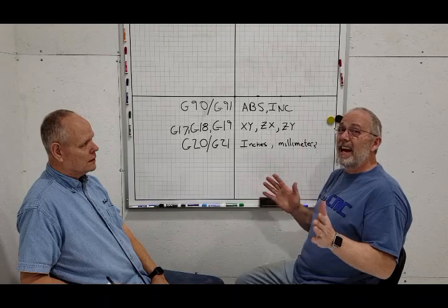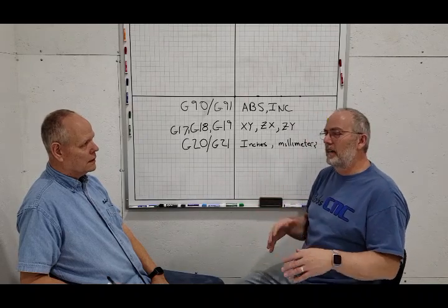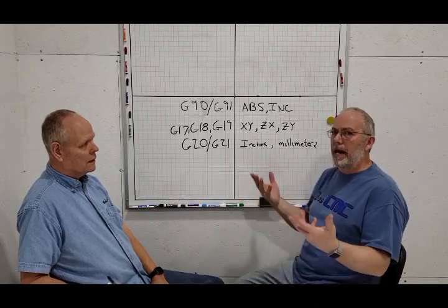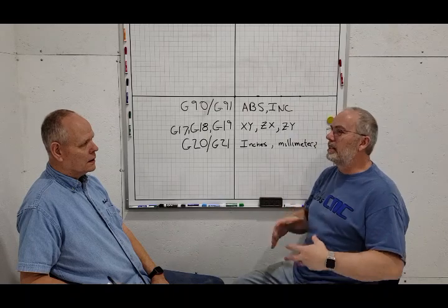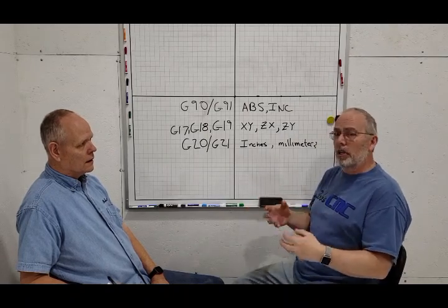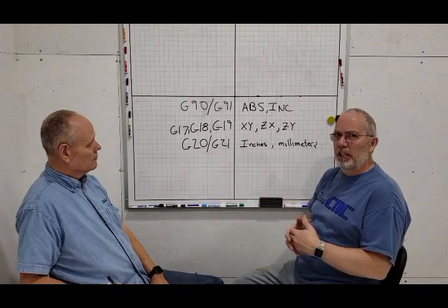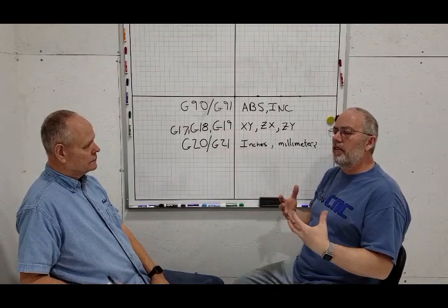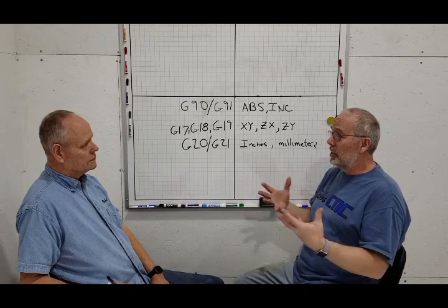The first thing I have to tell you is that a G-code file isn't magic. It really is XYZ coordinates with some feed rates and some other codes, which are normally letters like G, M, X, Y, or Z, that just tell the machine what to do.